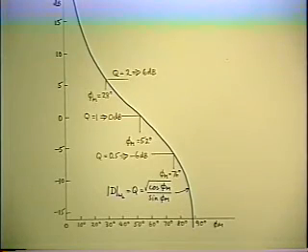Okay, well, looking at this picture showing the peaking factor, the Q factor of the closed loop response as a function of the phase margin, which is a property of the loop gain. And the important thing is how much phase margin you need in order to get an acceptable response.